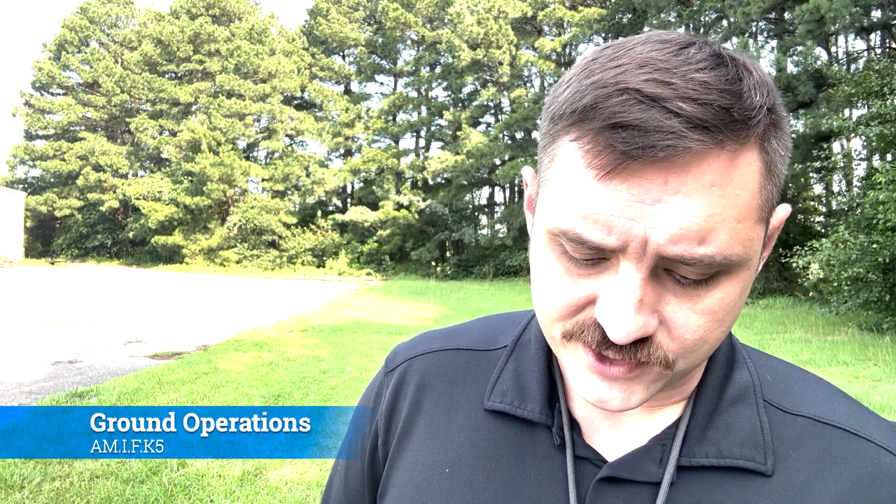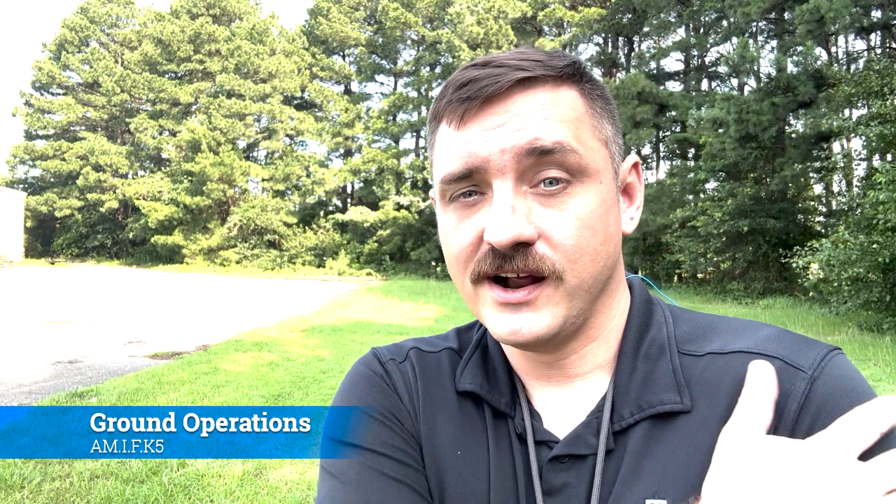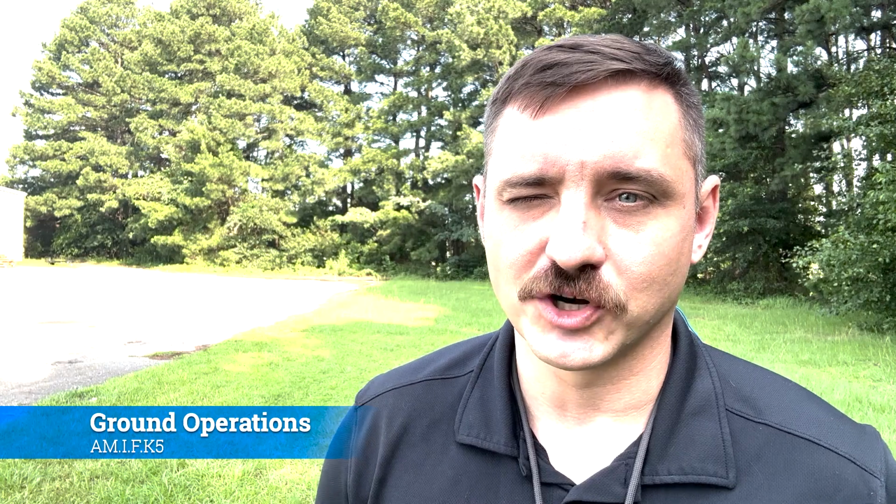If the aircraft is turbine engine powered, the area in front of the jet inlet must be kept clear of personnel, property, and/or FOD. Now, this is a big one for turbofan engines. So let's say you're cranking a 737 or 777 or something like that. That engine inlet is extremely powerful, so it's going to suck things in. You'll see guys that are standing too close to it, their clothes will start to flap as that turbine starts to spin.